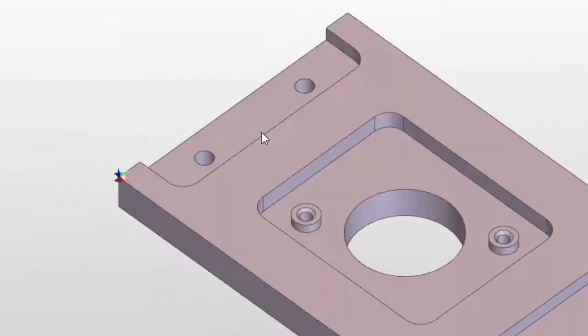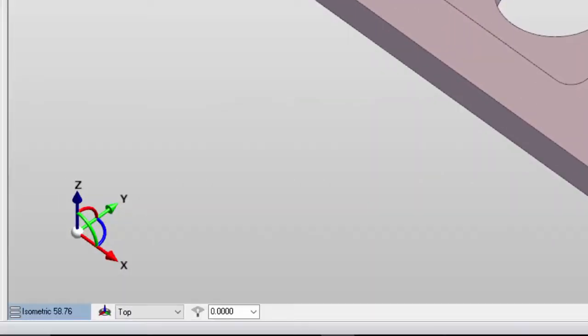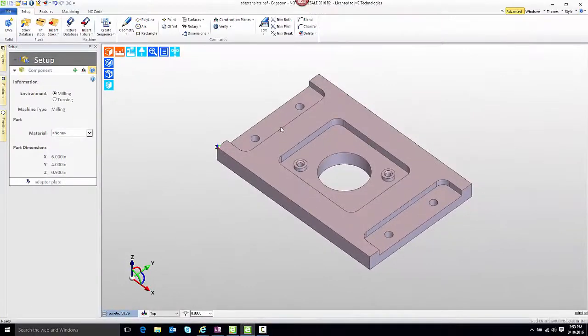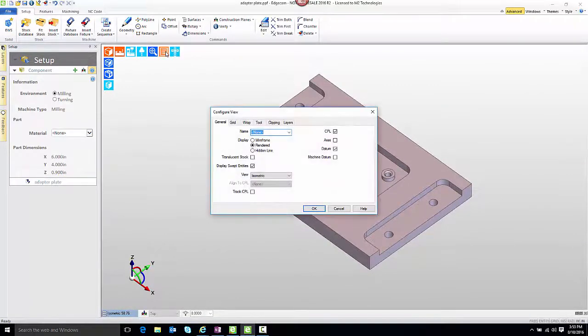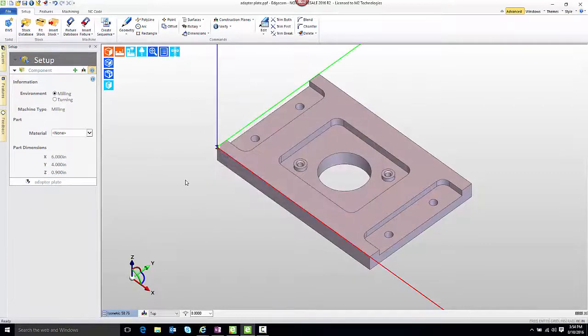So with some changes made, after pressing OK, notice that when we look at the Z-level field, it is now reporting 4 units to the right of the decimal point. Again, a visual indicator of system tolerance. Let's add a couple more minor adjustments. We'll go to View Properties and turn on Axis, which lengthens the visual display of the red X, green Y, and blue Z at the work system indicator. And then we'll choose a top view.